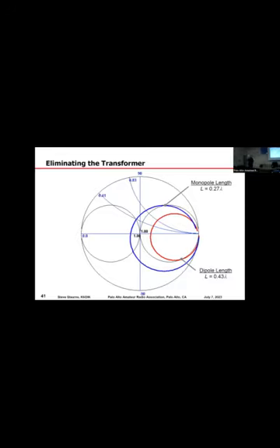If I was doing this with monopoles, I'd do the same thing. I'd cut the monopole a little bit longer than a quarter wavelength, because I want its impedance to land on the unit resistance circle on the Smith chart, where the blue curve crosses that circle. And so I end up with a 0.27 wavelength monopole over infinite ground plane. Now that's just to get the real part of the impedance to be 50 ohms. Now I've got the reactance of the antenna to deal with.